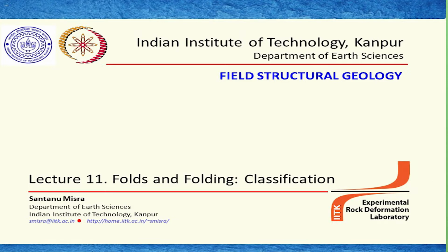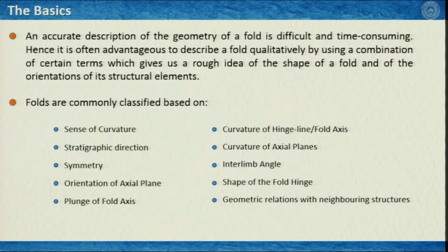Let's get started. Folds are commonly classified based on a series of parameters, and here I listed a few which I will cover in this lecture. These include the sense of curvature of the fold or form surface of this fold. Then stratigraphic direction, we will consider that as well, whether the fold core is representing young layers or older layers. Then folds also have symmetry because it is some sort of sinuous. So, whether the fold is symmetric or asymmetric, we will also test that.